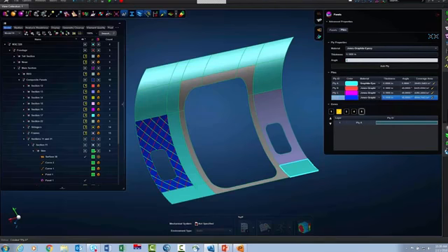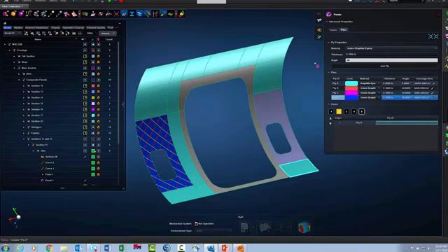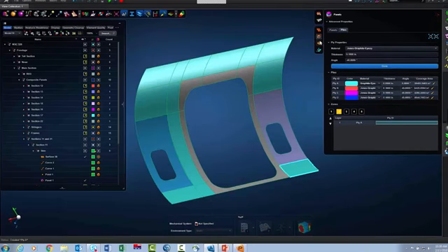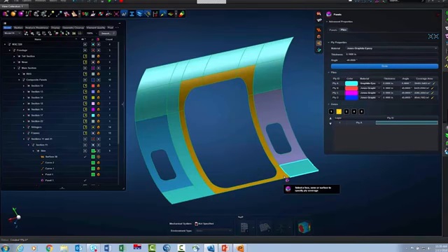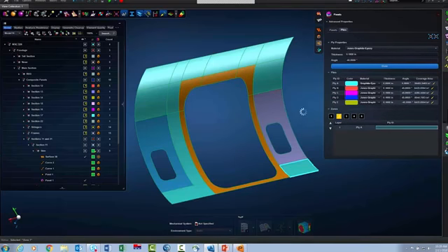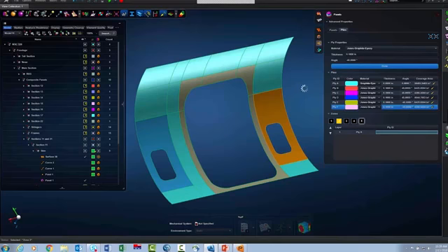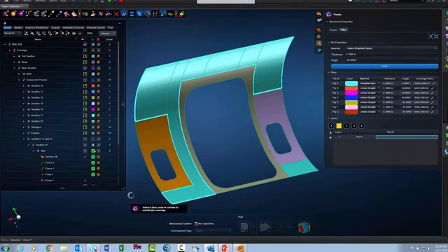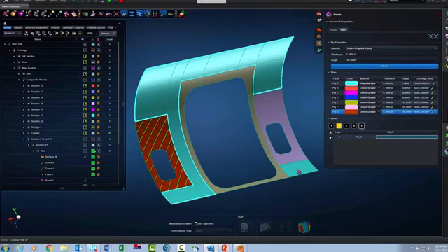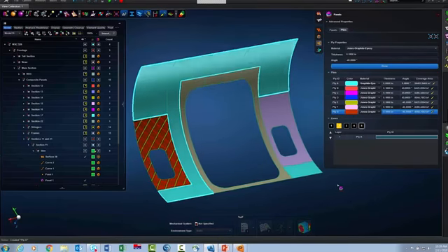So let's go ahead. We want to use our 45s in pairs. So let's do a -45, and let's put one around the door. Since I've already laid a ply there, that's already a zone. I can just select a zone. That'll be a little quicker. So I'll put a -45 around the door. I'll put a -45 around this window. I know some of these I could combine, but I'm actually separating them out so I'll get a few additional zones to manage.